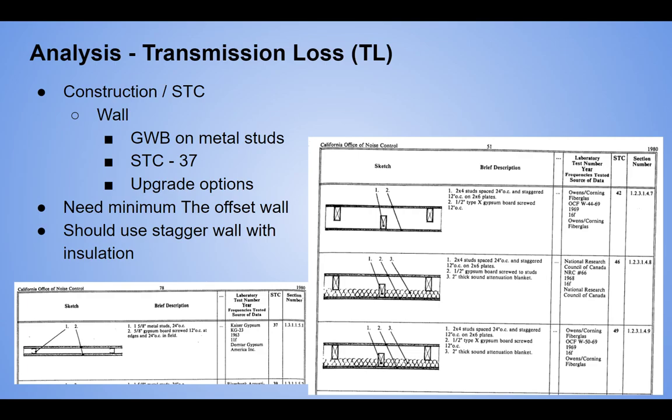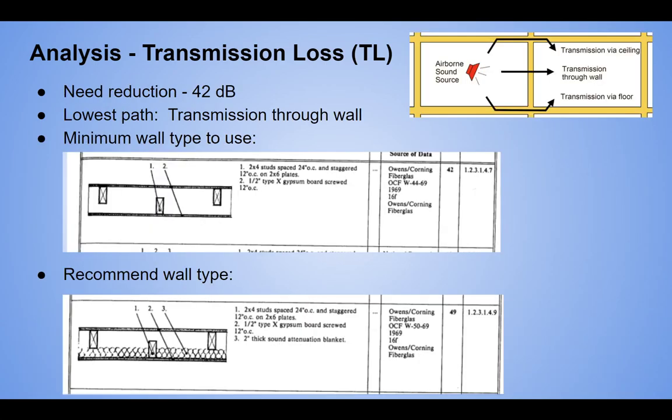So now we can look at it. If we're good on the walls, we might be able to have a thinner slab or a different ceiling type on there and be able to save money there. So the money that we spend here on the wall, upgrading this low-end wall to a better performing wall, we can then take those expenses, take it back to the floor, the ceiling, and do a value cost savings there. And so maybe we improve the wall, change what the floor is, and that cost offsets it, and then we have a much better acoustic environment.